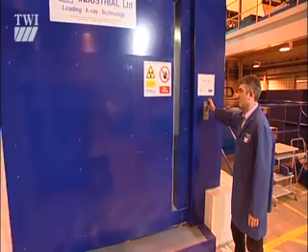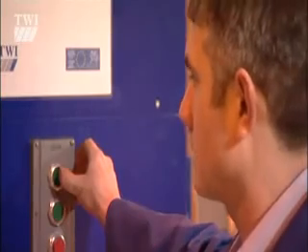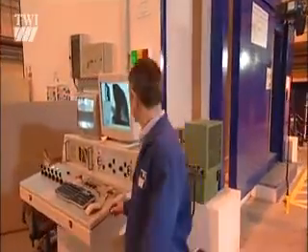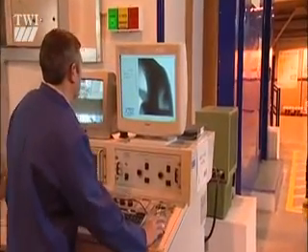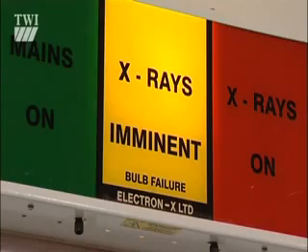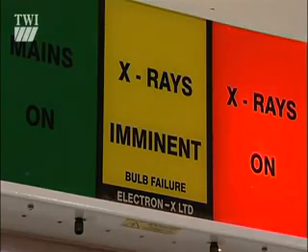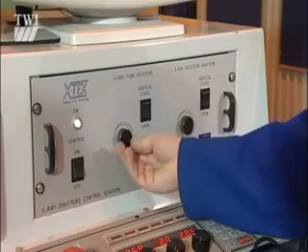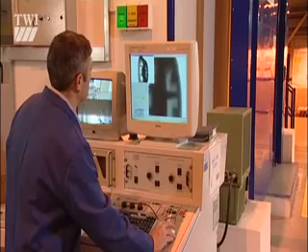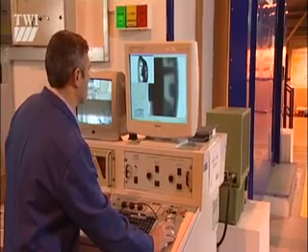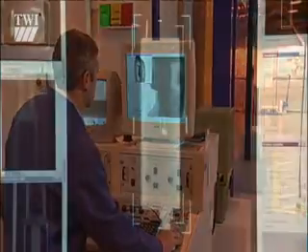During testing, a fluorescent-coated surface is placed behind the test specimen. As the radiation passes through the specimen, it causes different levels of fluorescence to occur on the coated surface, depending on the dosage received, and this is controlled by the specimen geometry. This is then converted to a digital signal and displayed on a screen.